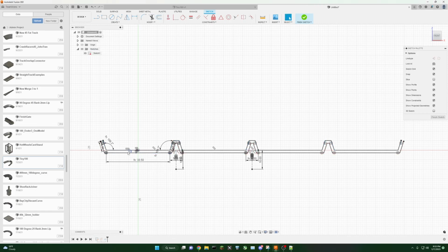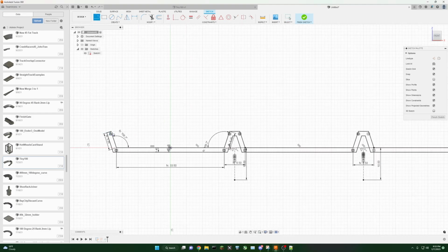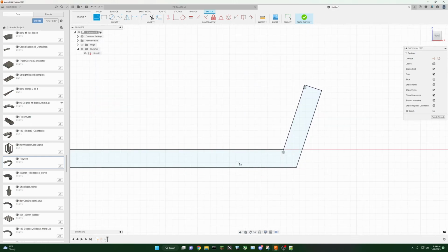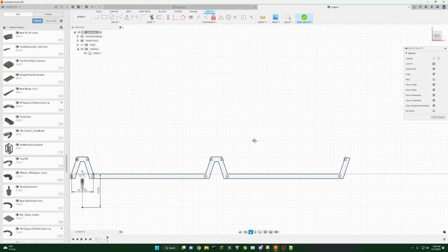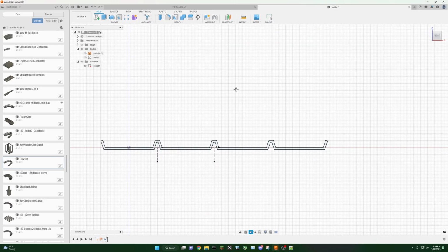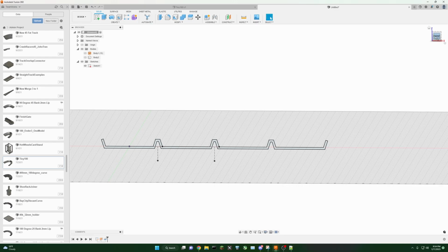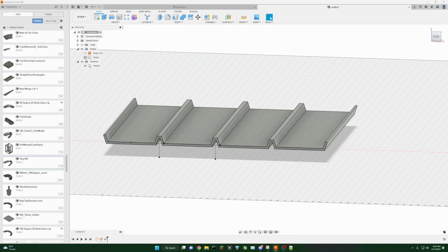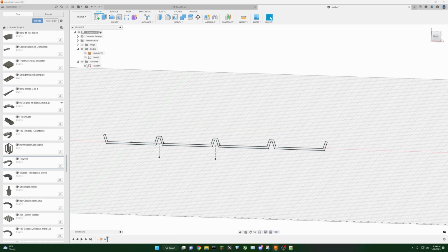Okay, and we haven't added this to our user parameters yet, but we had already gone over those user parameters. So we're going to connect these up to close this sketch, this profile, and you notice it changes color. Now it's dark. That means that it is a fully enclosed sketch. So when we've done that, we come back out, and Fusion 360 put our cursor back here at the end, which means we've still created these other guys, even though we already created these meshes and stuff. So if you look here, you see that. Those were both created from using just part of that profile we sketched. But now we have this profile.